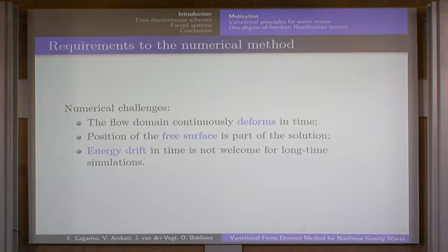We took the challenge. Why is it actually a challenge? A computational domain is moving, accommodating both the movement of the free surface and the wavemaker motion. Moreover, the position of the free surface is a part of the solution itself. Also, as we are going to work with long time simulations and waves will be propagating over long space, numerical energy drift is something you want to avoid. Otherwise, the wave will die too early and then we will not be capable of reproducing the experiment at the required place.